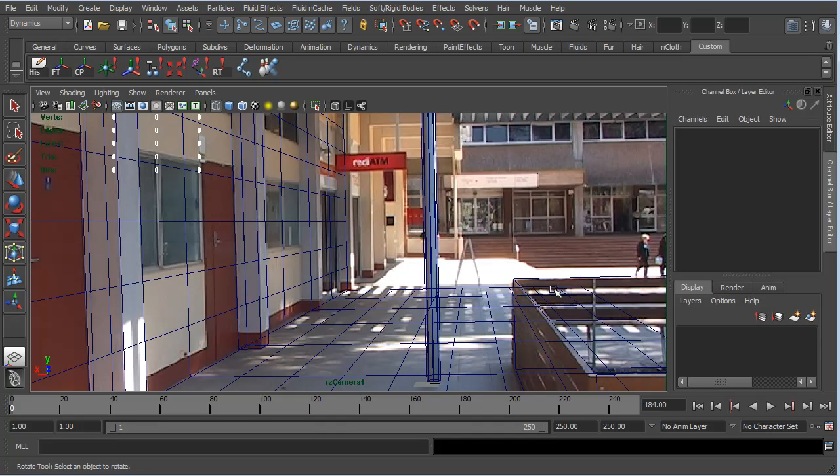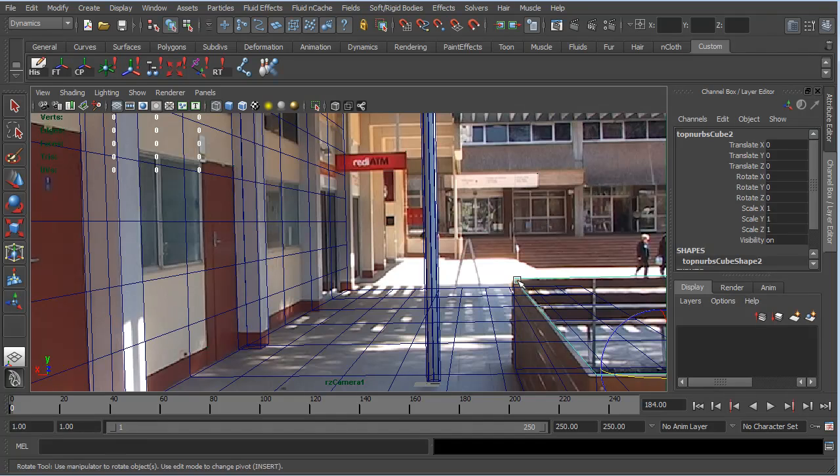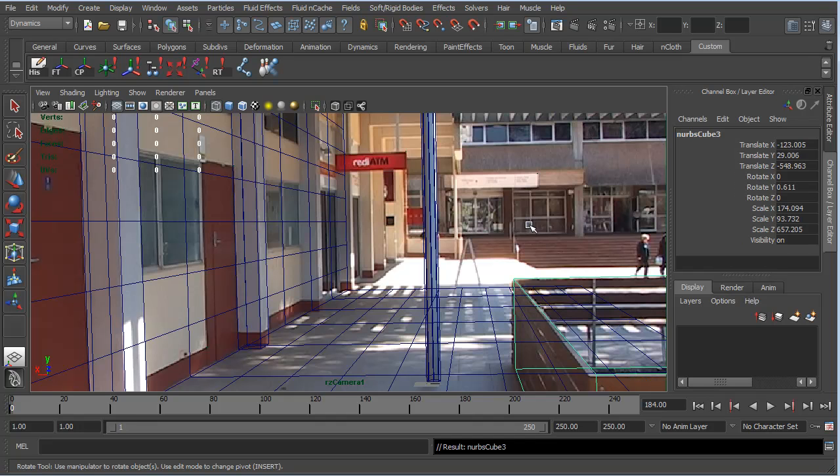Okay, so I might just try and get this cube lined up just a little bit better. So I'll just select that face, tap up to select the cube group, and I'll just grab this rotate Y. I'll click on it in the channel box, and I'll middle mouse drag in the viewport just to see if we can get a bit more parallel. And it looks like it's closest when we get to about 0.25. So I'm just going to enter that in this box here.